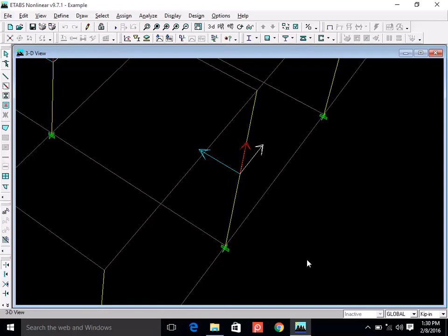Okay, I mean to say shear forces and bending moment, which is different from the beams. In case of beams, generally the loading is gravity, and earthquakes affect columns much more than beams. So in case of beams, our shear force mostly is about axis number 2. If you see shear 3, horizontal shear, that will either be absent or it may be absolute minimum. So in case of beams, only axis 2 is important for shear and axis 3 is important for bending. But in case of columns, shear can have components in both the directions, 2 and 3. Moment can be about both the axes, axis 2 and axis 3.